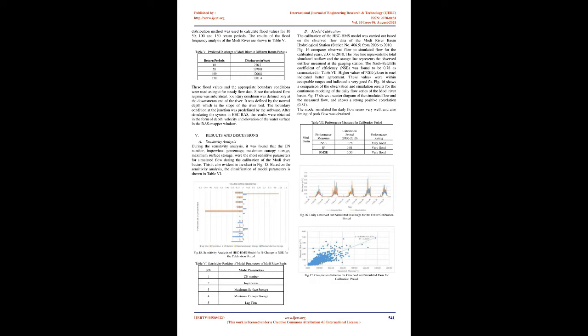HEC-HMS Calibration and Validation. Once all the parameters were assigned as input in the HEC-HMS project of the basin, output was obtained as the simulated flow values, which were then compared with the observed data over the same period to determine the consistency of the result.